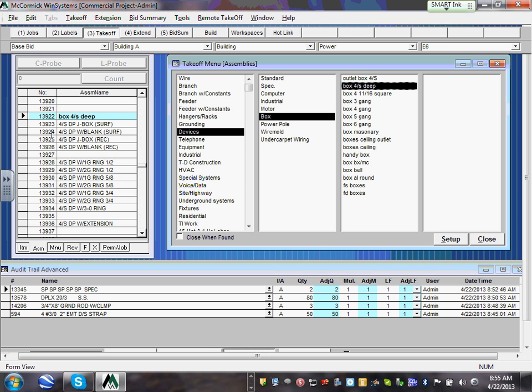Well, this is the box that you're going to put right here in the ceiling to bring the conduit to it, for grouping. You're going to put a box here, bring the EMT conduit to it, and take an MC cable to feed all your lights. You have to accommodate for that box. That's not a box where the receptacles are going to sit. That's already included in the takeoff.